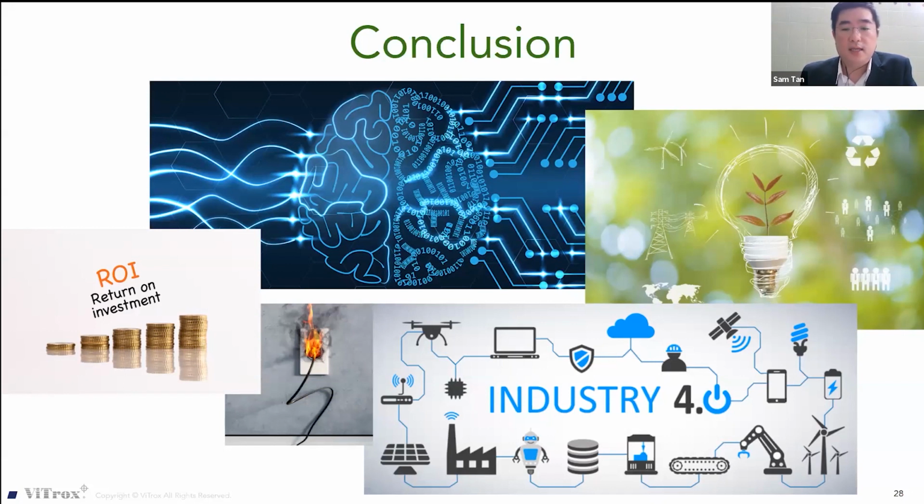Energy management can start easy, and you can move forward with the industry concept into it. So the investment is definitely worth it, with my experience. Some companies have actually earned back their investment within a year, especially industrial users that have never touched energy management before. From the research and our own experience, basically 10 to 20% of energy saving can be easily achieved by a beginner. And in the long run, energy improvement every year can reach 3 to 8% annually.